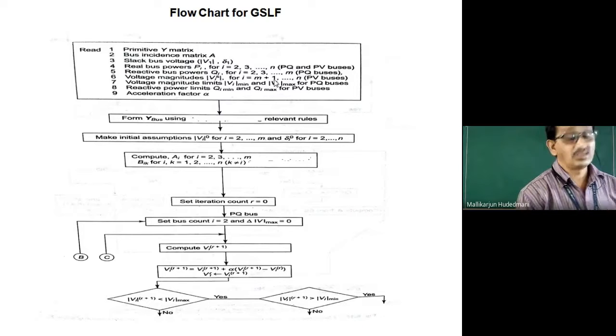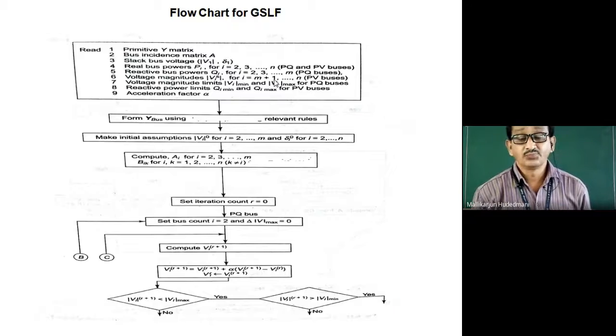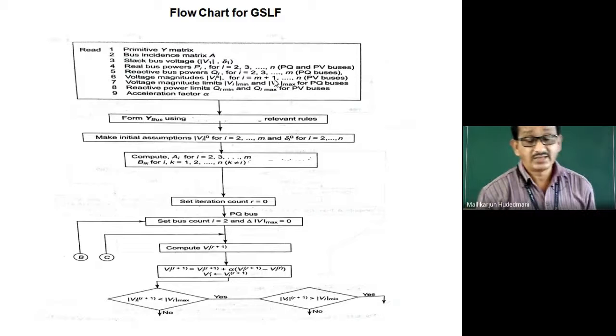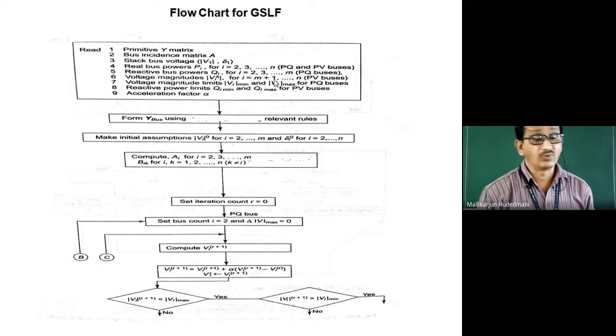So you may be having a question. What are the important data sets required for the load flow study? You have to write an answer. Data sets required for the load flow study are as follows. System size, the number of buses in the system should be known to me because that limits my Y bus dimension. Number of buses in the system gives me how many terminals are there in your system.